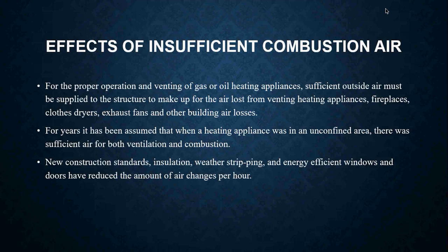Today, no, that's not really the case. These houses are being built to different standards. They're being built tighter, with more insulation, with more weather barriers, where you're reducing the amount of air changes per hour in a home. So now we have to start thinking about mechanical means to bring in the air that we need to help support the combustion of these types of appliances, so that we don't have smoke and soot and odors coming out of these things when they're burning.